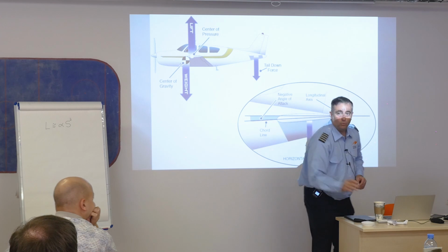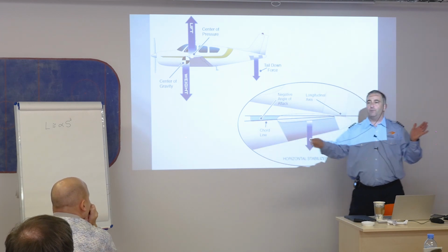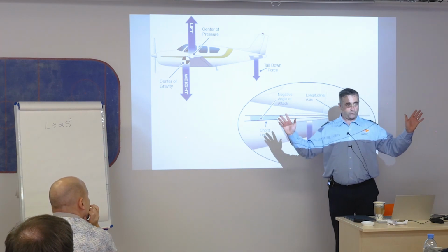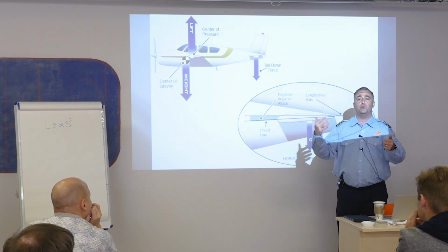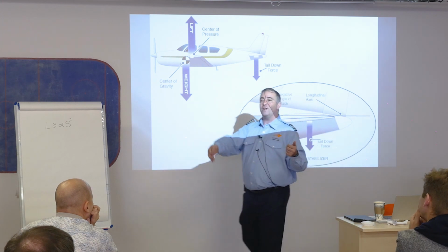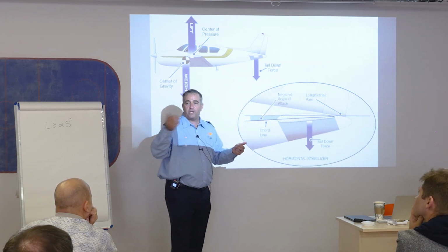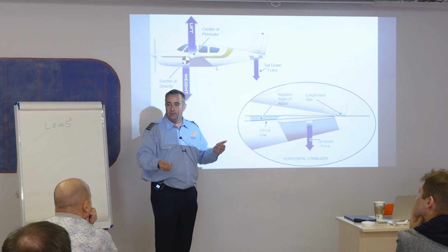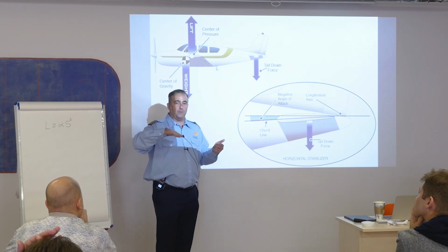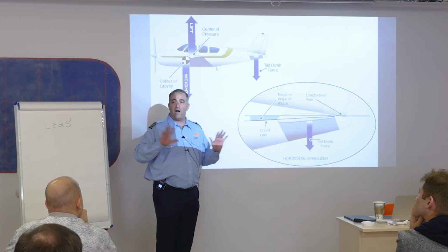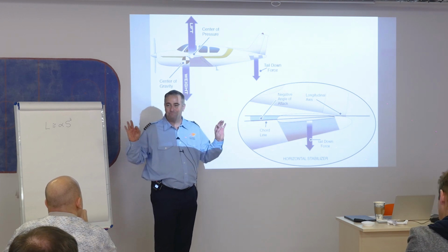The idea is, what did I try to do with this airplane by reducing power? I haven't touched any controls yet. I have my hands on the controls, but I'm not pushing any pressure. So what have I done with this airplane? I've initiated a descent. Okay? Decrease my power, right? And the nose of the airplane decreases by itself.